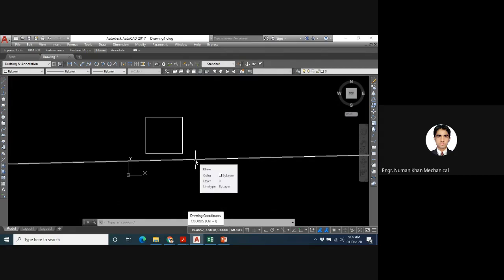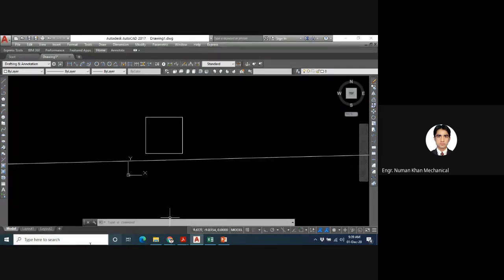If you remember, while drawing the first angle or third angle of projections, you were using some kind of projection lines from one view to another view. Those lines were there just for projection purpose, and when you complete your projection, you remove them. So we use this type of lines to construct something. I will show you how we use it for the construction of different types of things.